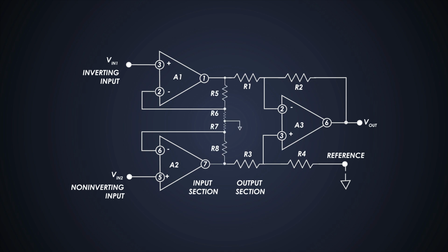We add multiple resistors, which increases the gain equally for differential signals. If you look closely, these op-amp circuits look like non-inverting amplifiers. Now we can refine this circuit mode, which will look something like this, and it is the classic 3 op-amp instrumentation amplifier circuit, which we'll see in this video.